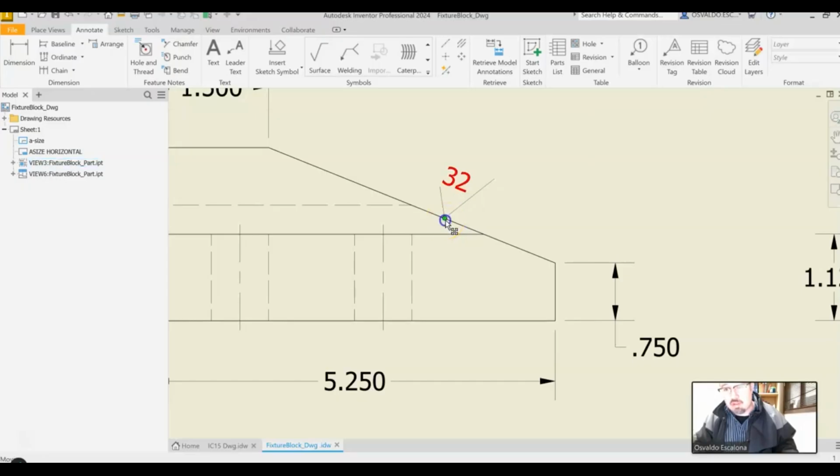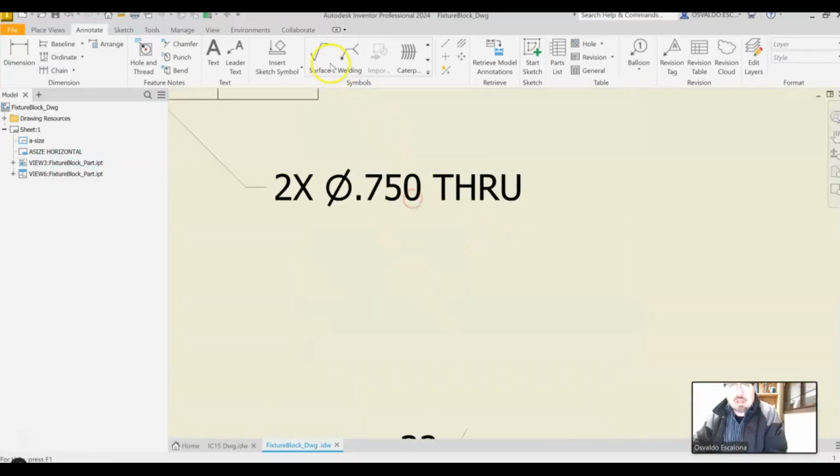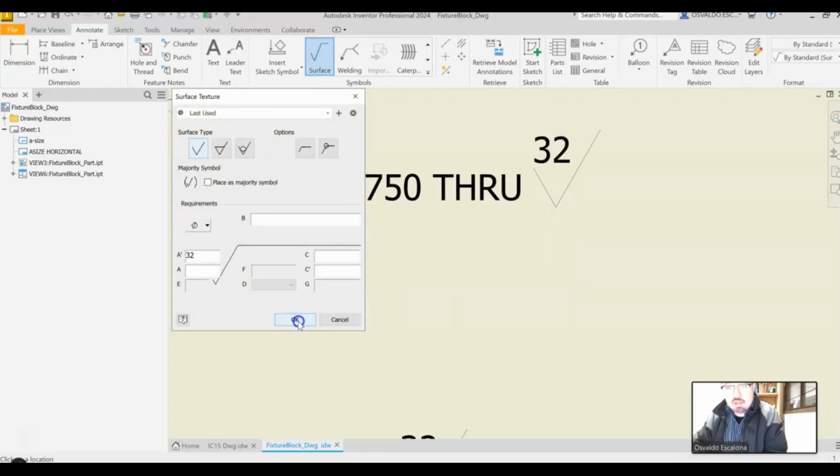So by that point of time, you can do a couple of things. You can grab that dot and you can move it to the side, right? Anywhere here. And if you want to make a leader, you push it to the side and then you lift it up. Boom, done. That's how you make it surface finish. If you want to put it on the hole, you come over here and then you double click super quick. Boom, boom. And then usually when retain the last number, you say okay.